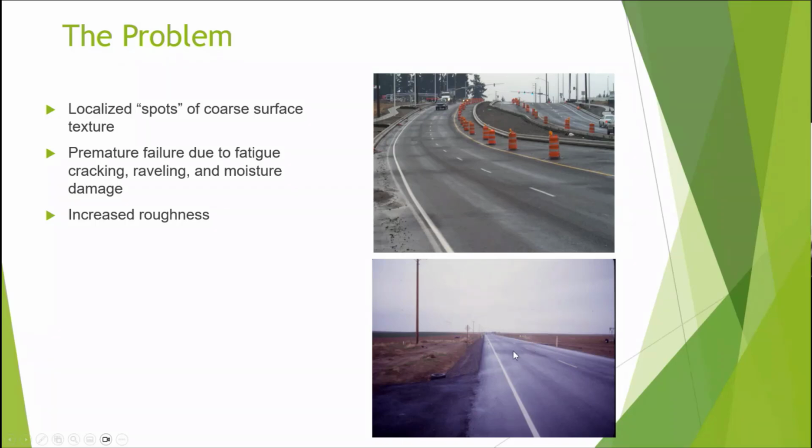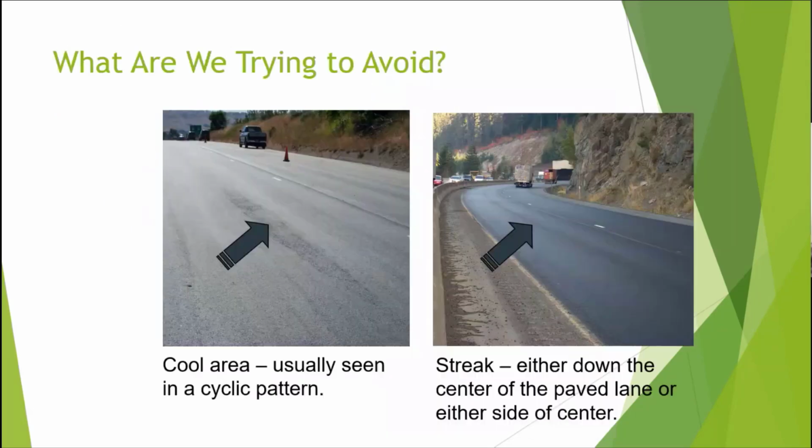Now it's rain, but it's not raining now, so things are starting to dry out. And you see these dark spots? Sure sign of low density or high air voids, because that moisture should be a sheen, just like a specimen or core or a gyro sample in SSD condition. And that moisture is disappearing into the pavement.